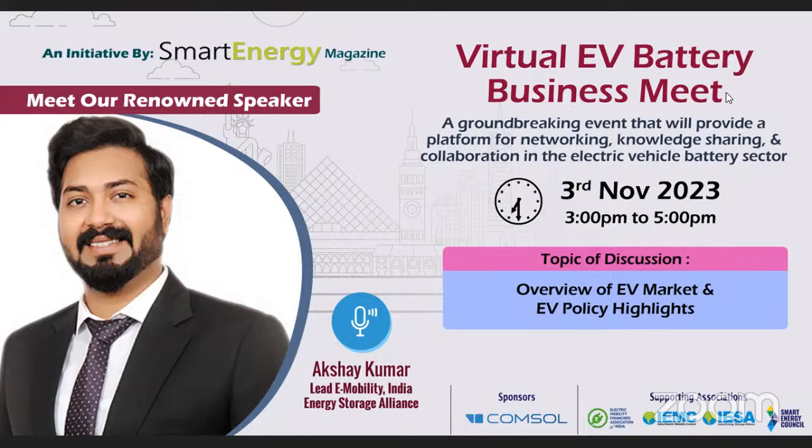But for energy storage, the projects which are already in the pipeline and lots of tenders, UPCCL and other SECI projects, if you see, they talk about 12 years O&M and 12 years of warranty and 12 years of OPEX model along with the CAPEX. So definitely one has to go for high energy cells, which have very low energy density compared to their same model for mobility. So 10,000 cycles, 20,000 cycles, 6,000 cycles is always at the trade-off of energy density.